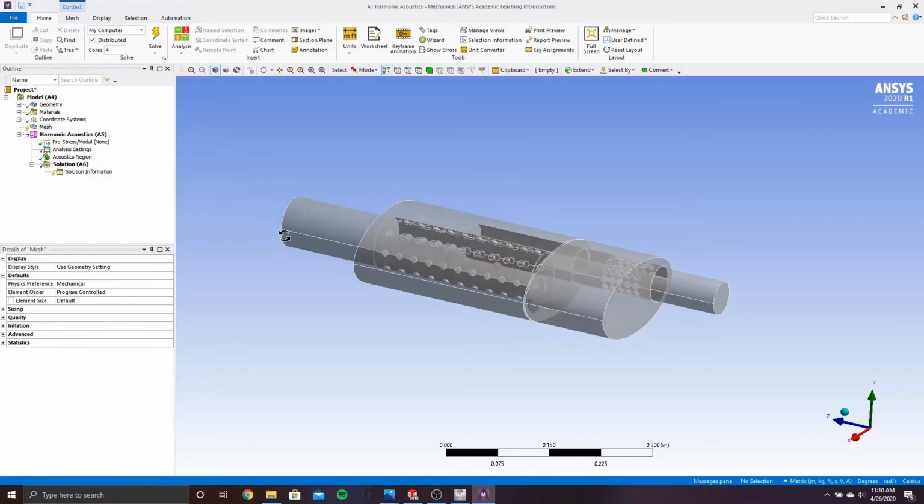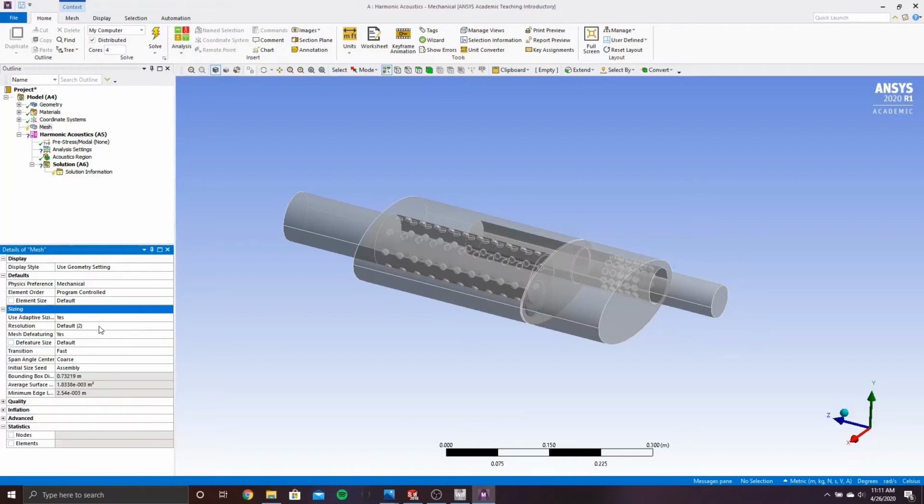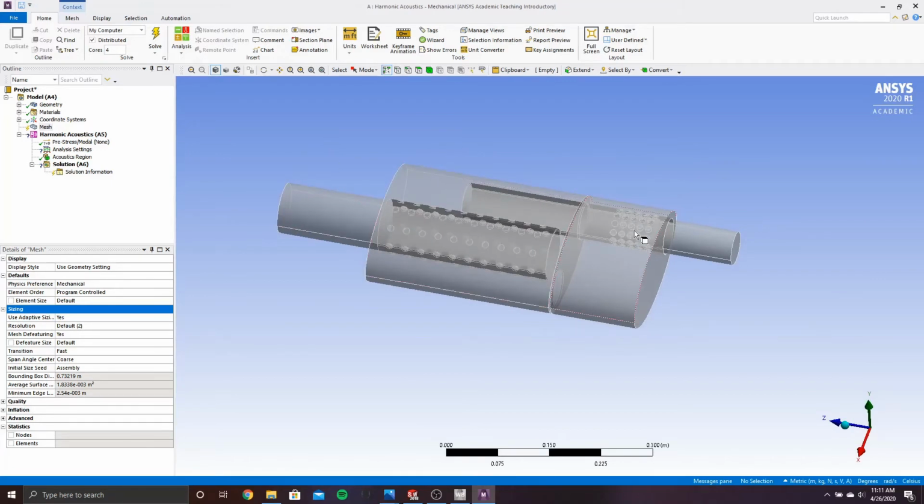So an important thing to consider with the mesh, if you have ANSYS Student Edition, which I do, is you're limited to less than 32,000 nodes or elements. Not the sum of the two, but individually, neither can exceed 32,000. So in our case, we'll need to change some of these element properties to give us a more coarse mesh. Otherwise, we'll run past our requirement too quickly due to this relatively tight internal geometry specifically.